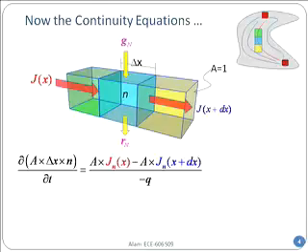So G sub n and R sub n represent electron generation and electron recombination, through trap-assisted recombination or direct recombination, that type of thing. And so all you have to do is again multiply with the volume and the Gn, because what is Gn? That's the number per centimeter cube per second. So that's the generation rate and correspondingly the recombination rate.